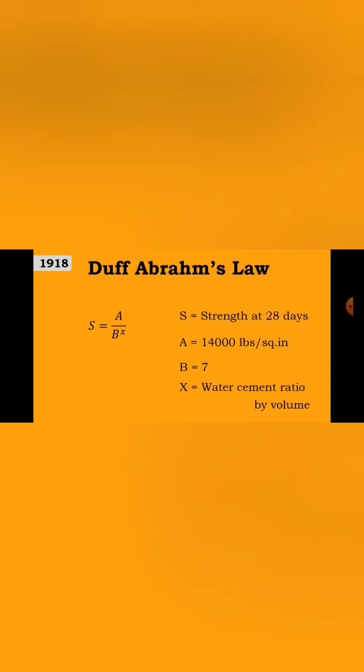According to this, it is going to indicate the complete plasticity law of the concrete. From all these things, we can conclude that if the water content or the water cement ratio is more, strength will be less, and if the water cement ratio is less, automatically strength will be more. But to attain more strength in high performance and high strength concrete, we will go for lesser water content, and we are going to tackle the problem of improper consistency and lesser workability by using admixtures.